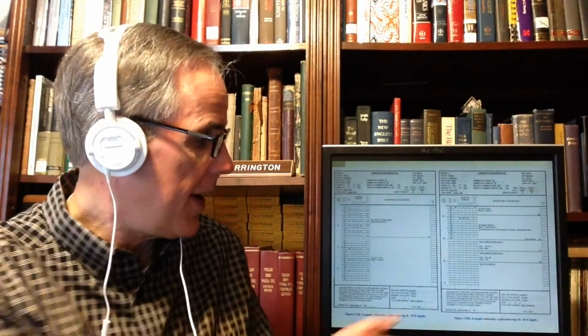One thing you'll notice at the end of this is an RQD. When you get down to rock, somebody might like to know the rock quality designation, and we talked about that in the first lecture. You'll see those on boring logs fairly frequently. In some cases you'll have more than one, where you have a rock quality up here, and then one there, and one there. So there are many different things that you can see on these boring logs, and they're arranged in different ways, but the results should be the same.